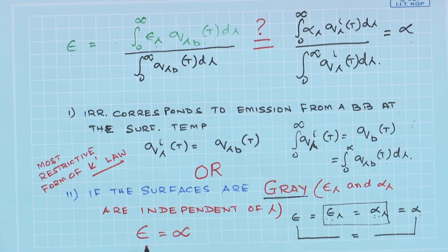So, calculations for radiation exchange between surfaces are greatly simplified if this can be assumed to be true. Most of the calculations of radiation between 2 or 3 surfaces, when they are exchanging radiation among themselves, are greatly simplified if we can assume that they are gray surfaces. Fortunately, for many of the engineering surfaces, the assumption of gray behavior does not incorporate significant errors.